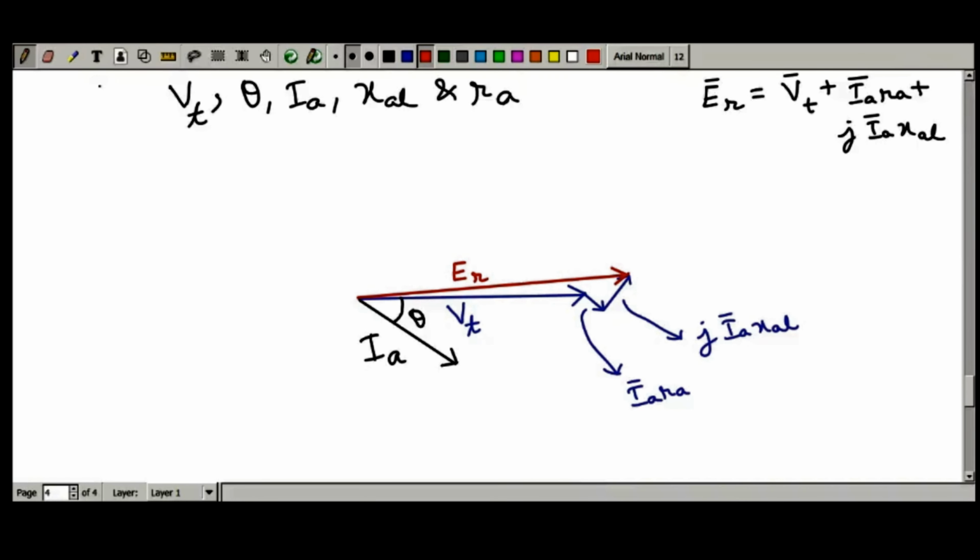Now if you go by this equation, let me write the equation. What was the equation? That air gap voltage Er equals the no load EMF Ef plus Ear, isn't it? So if you go by this, then you have to add Ear. First of all, what is Ear? It is produced due to the armature flux phi A, right?